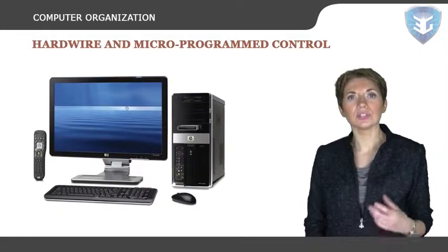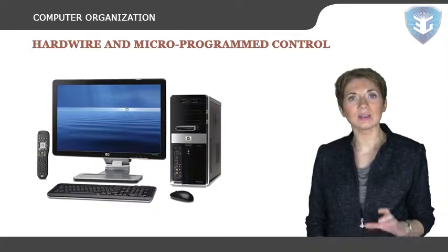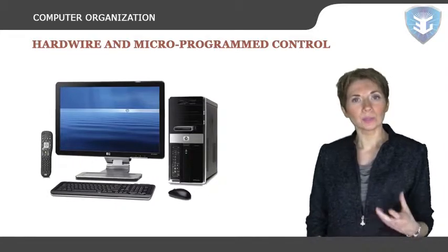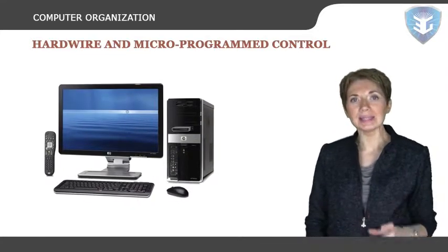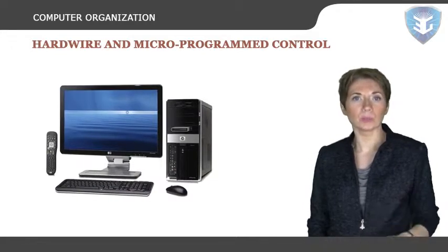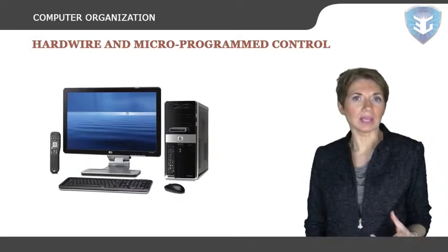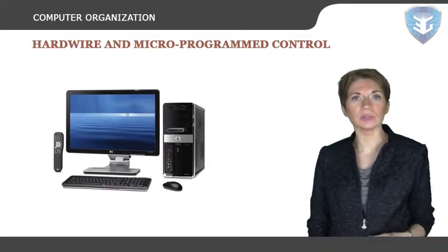Another advantage of microprogrammed control is that the task of designing the computer in the first place is simplified. The process of specifying the architecture and instruction set is now one of software, microprogramming, as opposed to hardware design. Nevertheless, for certain applications, hardwired computers are still used.